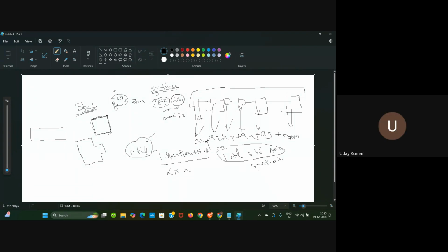If the design results are good and converging very easily, then they will increase this utilization. Let us say they increase it to 85%, because at 65% the design was meeting very easily and the turnaround time is very small. What made them increase to 85%?